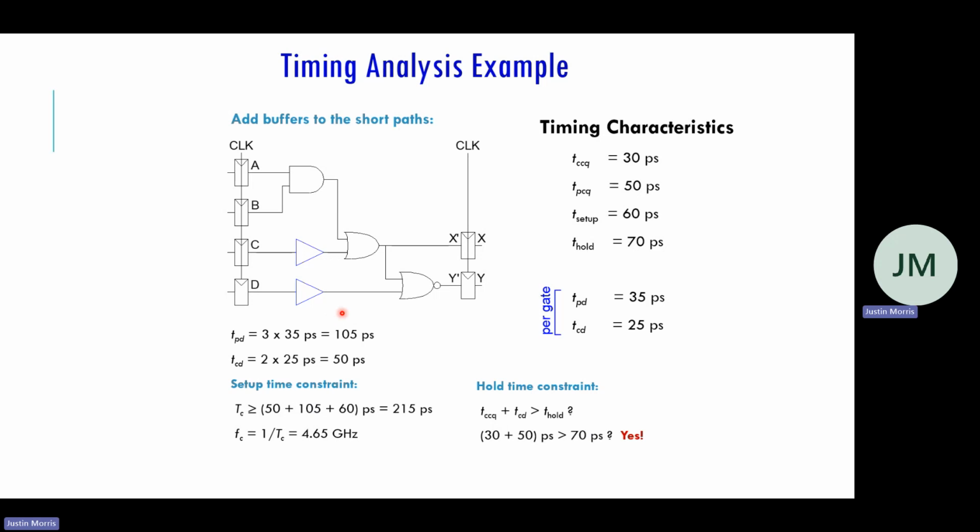So it is possible that adding these buffers will require you to impact your performance in terms of your cycle time, but in this case, it did not impact it. And we just now have a correct circuit for all input combinations. So that's how you can fix it.